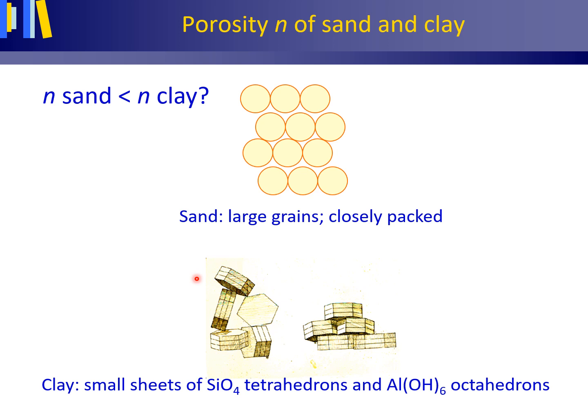Thin films of water and neutralizing cations adhere to the clay mineral surface by electrostatic forces, and the same amount of water is held more strongly in clay than in sand, which is also why a sand layer in the subsurface can be quite permeable and clay and mudstone are not, why it is easier to remove water from a sand than clay layer, and why sand layers in the subsurface constitute the aquifers and clay layers the aquitards.